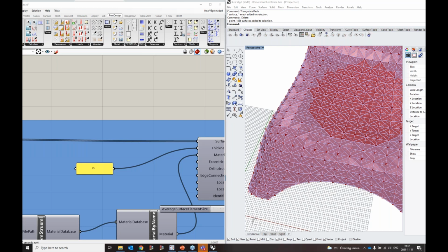And sometimes if you have a really complicated structure where a lot of different things have a big effect on each other, then maybe it's not suitable to deconstruct it into local models. But you could, of course, import the different internal forces from the global model into the local model. It could be any type of forces really, but you have to make a judgment of when it's suitable and when it's not.